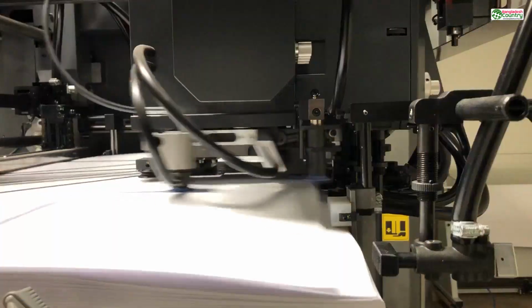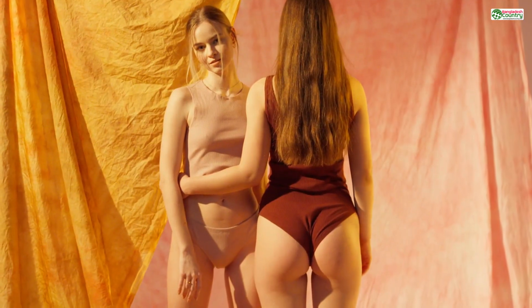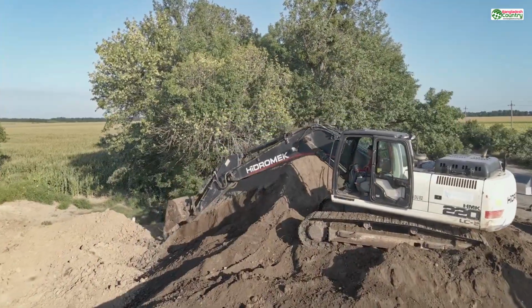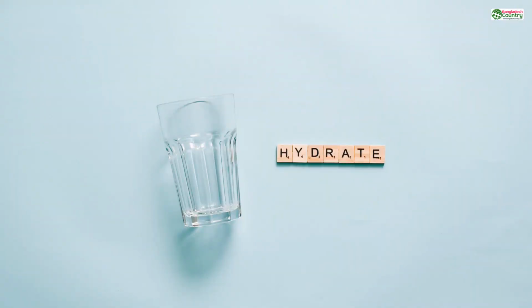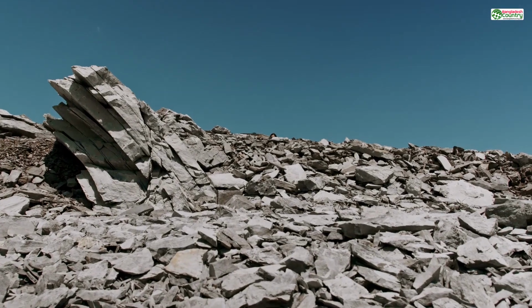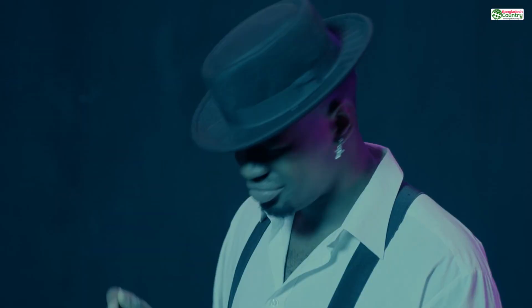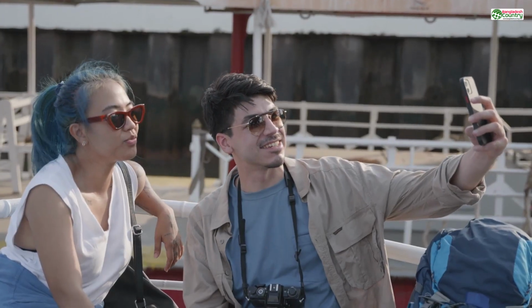After the print is done, your model is a solid object buried in a cake of fine powder. It has to be excavated, often using brushes and compressed air. If your walls are too thin, they are now impossibly fragile. Imagine trying to unearth a fossil made of meringue. The force of the air and the brushing will simply sandblast your delicate features into oblivion, or snap them right off. So what's the magic number?